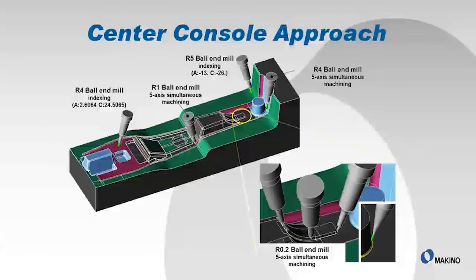You'll notice some of that's around that boss we talked about earlier, trying to get that back surface and the features that are down below the surface of the cavity, the core and cavity there. So we're trying to basically go after this part and provide the best surface finishes, blends and matches that we can, obviously for aesthetic purposes, but also we want to make this part as quickly as we can for productivity.